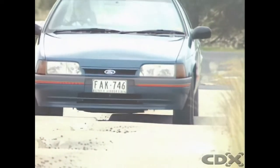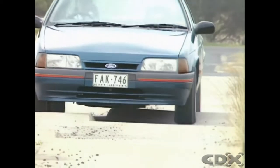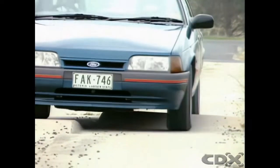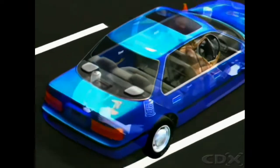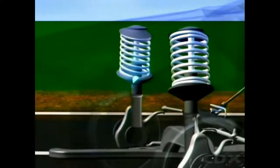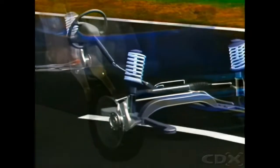The sprung mass is that part of the vehicle supported by the springs, such as the body, the frame, the engine, and associated parts. Unsprung mass includes the components that follow the road contours, such as wheels, tires, brake assemblies, and any part of the steering and suspension not supported by the springs. Vehicle ride and handling can be improved by keeping unsprung mass as low as possible.